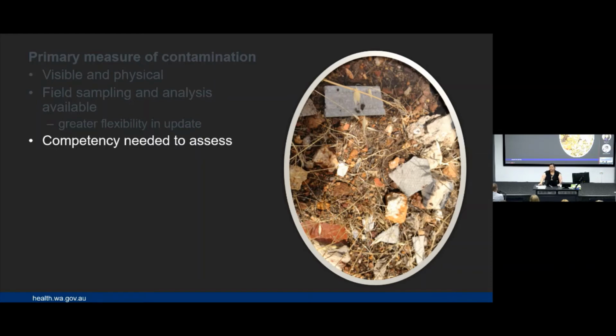Mostly people pick up asbestos cement, and field technicians are really great at spotting asbestos cement. But we have been on sites as officers where we've seen that, yep, they found the asbestos cement, but here's this friable product that they've completely missed. Maybe some rope seals or some fire blankets, completely missed, because the field technicians are only used to looking for asbestos cement. And arguably those products they've missed are more of a risk than the asbestos cement fragments.